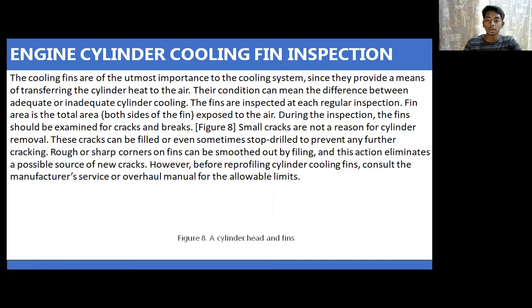Engine cylinder cooling fin inspection. The cooling fins are of the utmost importance to the cooling system, since they provide a means of transferring the cylinder heat to the air. Their condition can mean the difference between adequate or inadequate cylinder cooling. The fins are inspected at each regular inspection. Fin area is the total area, meaning both sides of the fin, exposed to air during the inspection.